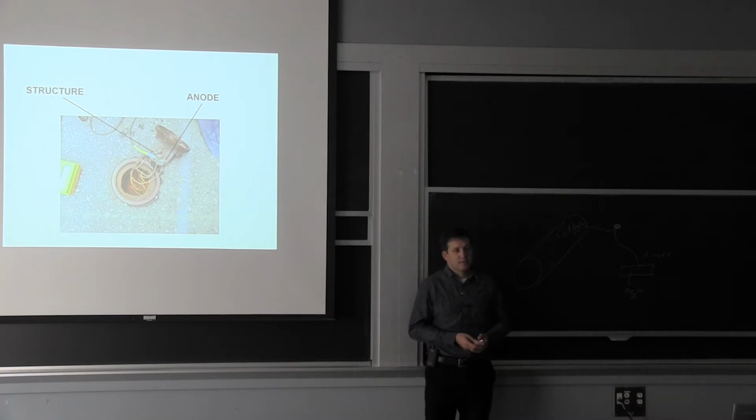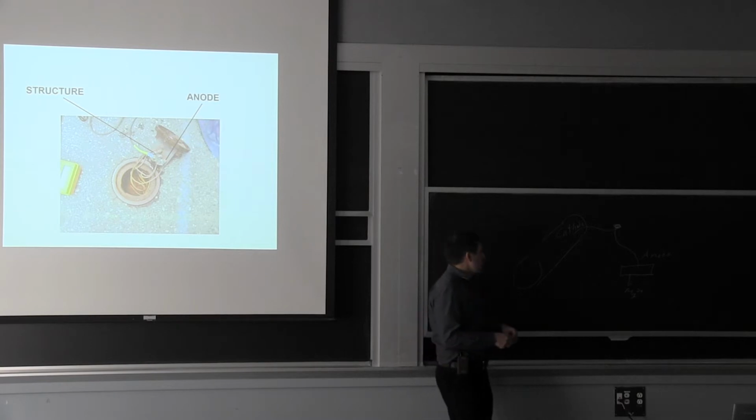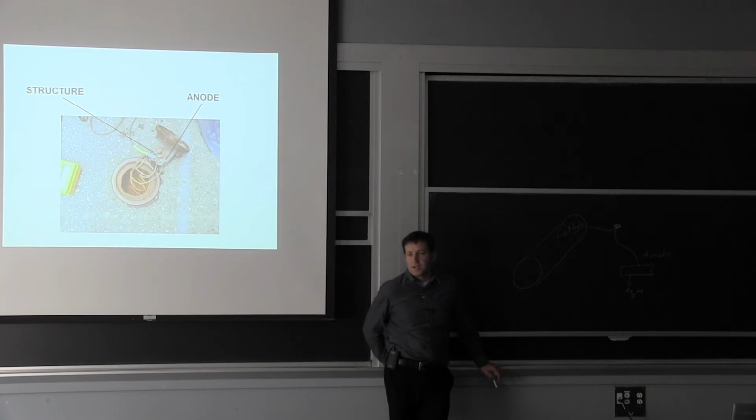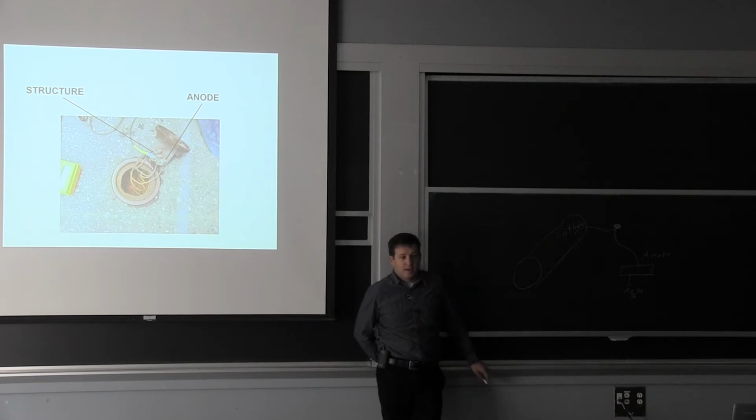Yes? Did you say you're producing hydrogen at the campus? You can. There are three reactions, and it depends on pH and your potential. So a very acidic environment is what leads you to a higher risk of forming the hydrogen here. What were the others? Just a recombination of water, and the third one I forgot. The one we worry about is producing atomic hydrogen. And some of these also depend on potential, so it depends if you're making iron 2 ions or iron 3 ions.